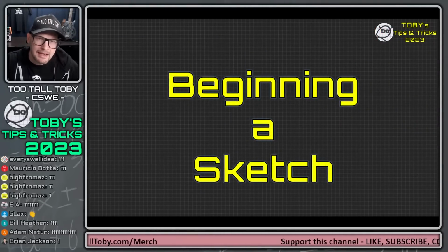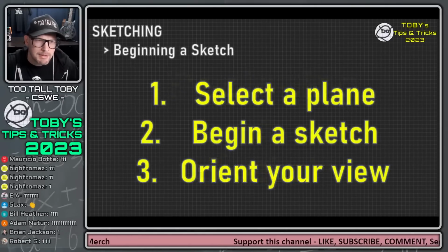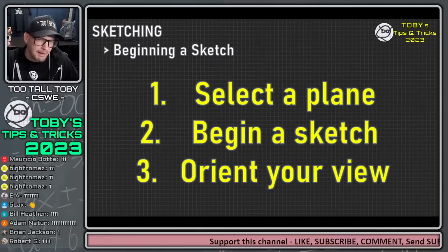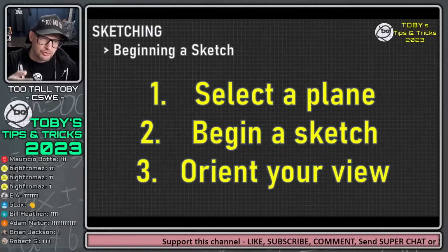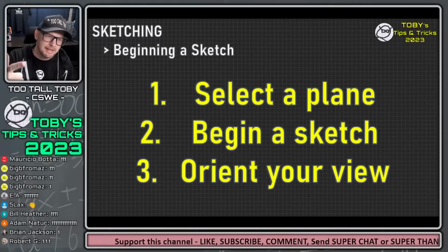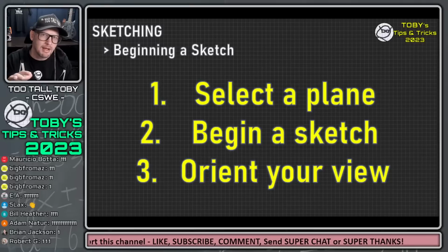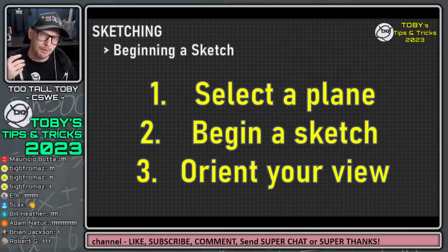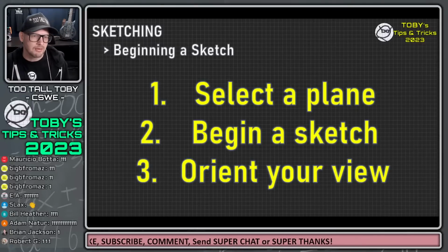is that beginning a sketch is often a time sink. And what I mean by that is, this is a mantra that I would always teach my students. I've taught hundreds of professional training classes, and I would always teach them this 3-step mantra: select the plane, begin a sketch, orient your view. It's so much that you often hear me saying it when I'm doing my tutorial videos. Select the plane, begin a sketch, orient your view.